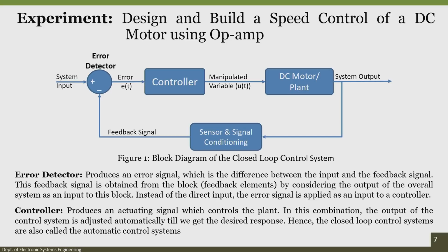But in the previous module we considered the DC motor RPM as frequency divided by 14, but we do not know whether it is going to give 14 pulses per one revolution or 7 pulses per revolution.